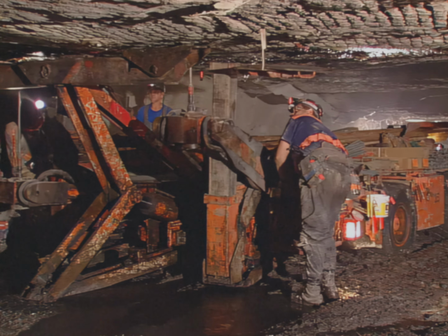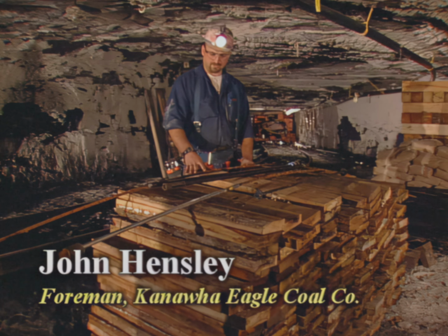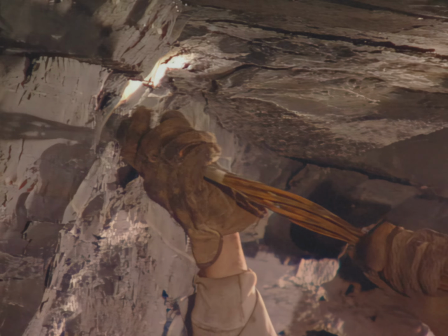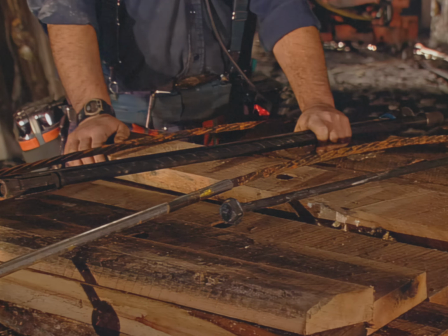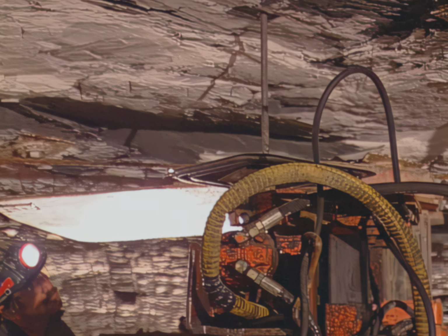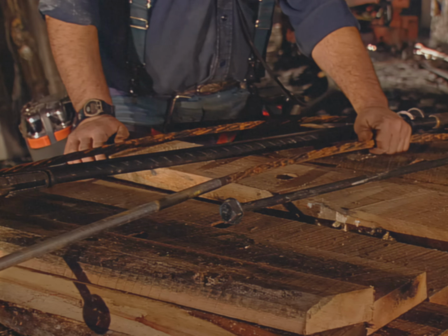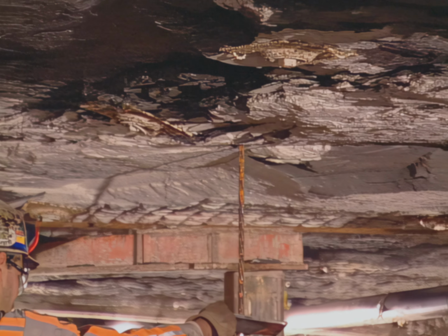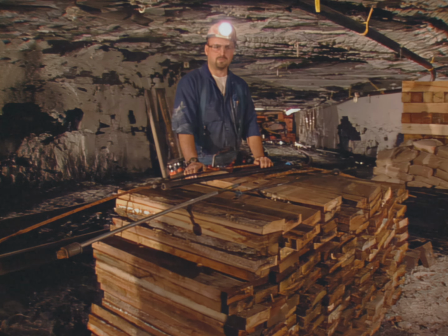Roof bolter operators today often install many kinds of high-quality roof support systems. The bolts we have here are some of the supplemental roof supports we use. This is a 7-foot cable truss. They're installed on a 45-degree angle to divert the weight of an entry back over the pillars. This is an 8-foot combination bolt. We use those in our intersections in a star pattern for added support on advancement, but it really helps out when we're pillaring. These are the 14-foot cable bolts that we use. They help when the different strata of rock separate above the 8-footers. And this is our 4-foot conventional bolts. We use those for rib bolting.